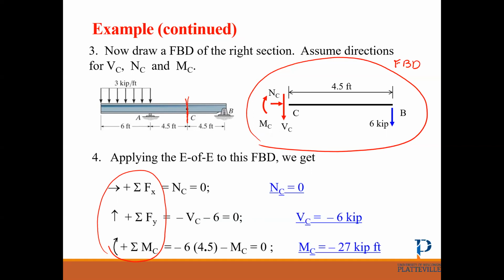All right, so let's just review the steps. First, find reactions. Second step, make a good cut. Third step is apply the equations of equilibrium. That's all to find internal forces. Internal forces is the most important topic in statics.